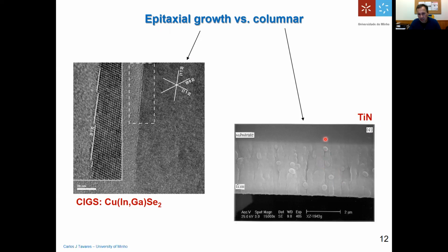And if you make it on glass, sometimes it's not the best option. Okay, you can make it on glass, just for example, to make analysis for a specific technique. But when you're considering making a titanium nitride thin film, then you're thinking about making the deposition on steel or carbide steel or other type of substrate or aluminum. And you really need to have an adhesion layer between your titanium nitride thin film and your substrate.